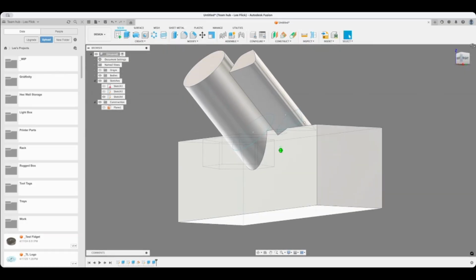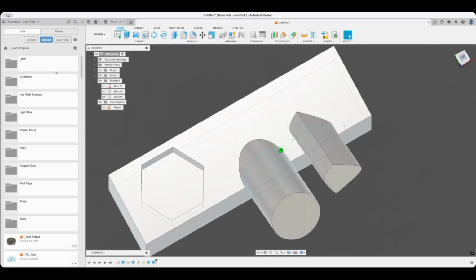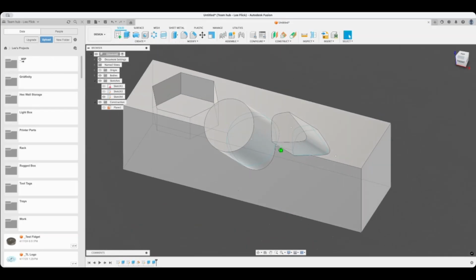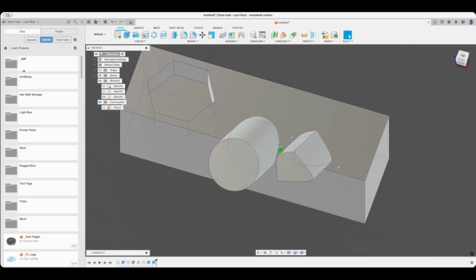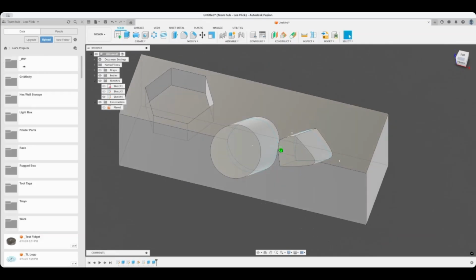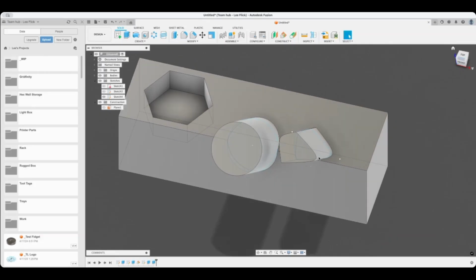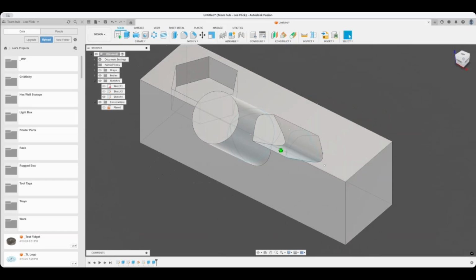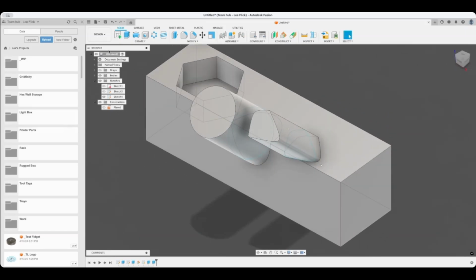So I did a sketch. I have my weird shape there. Did it turn light blue in the center? Yep, it's light blue. I click finish sketch, but then it disappears. Oh, okay. So go over here on the top left. Sketches. Go hit the little arrow next to sketch so it drops down like mine does, and put the little eyeball on for the last sketch.